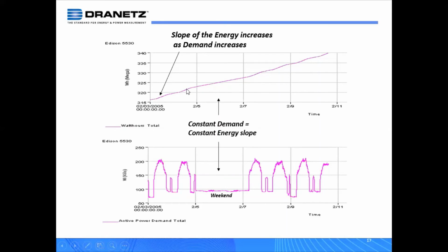And then going back here, these slopes that you see, that's what's known as the energy rate. The parallel I can draw, for those familiar with the old electromechanical kWh meters that have the spinning dial, is that the spinning dial represents the energy rate. If it's spinning very slowly, you're accumulating energy at a slower rate. If you have everything on in the house, like in my household, where people can't turn things off, then that dial is spinning very fast. So that's what these slopes represent. It's still accumulative, but how steep or shallow it is indicates the energy rate.